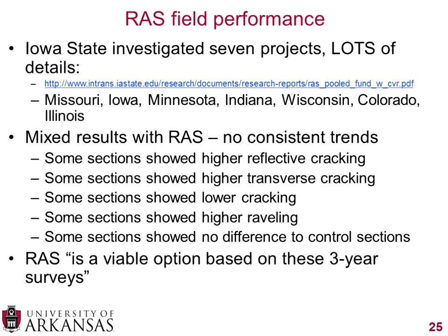Some sections did show higher raveling. That may go back to the fact that you don't have full blending going on, and if you have shingle particles that aren't fully blended and those are up at the top of the mixes, then that could start raveling off, and if you're expecting that asphalt cement content to help hold the aggregate together, then that would potentially lead to further raveling as well. So raveling is something to keep on your mind.